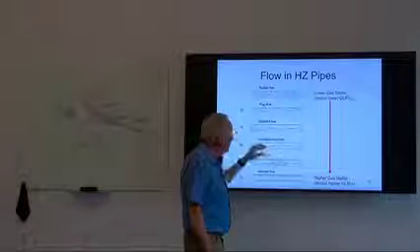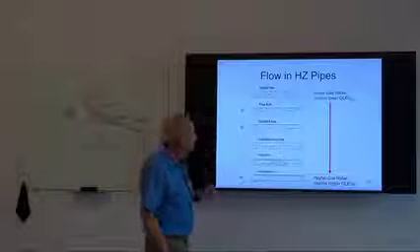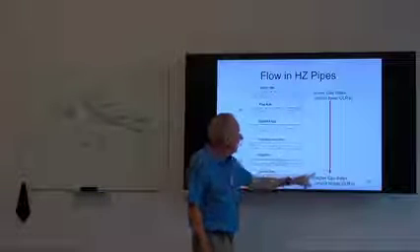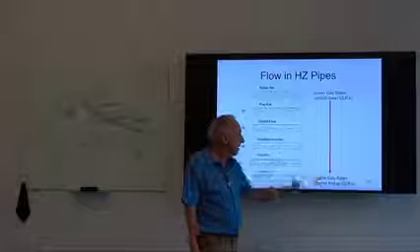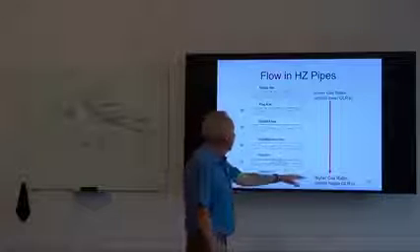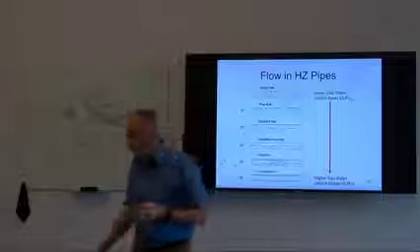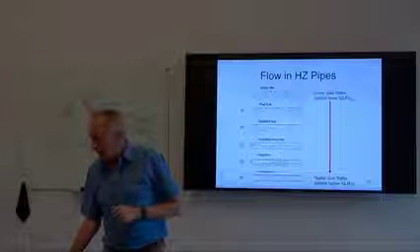Stratified, wavy, I mean, there's all kinds of descriptions of these things. But you can actually get to a point, even in a horizontal well, if you have a very high gas rate and/or a very high gas to liquid ratio, where you can essentially get this mist annular condition.